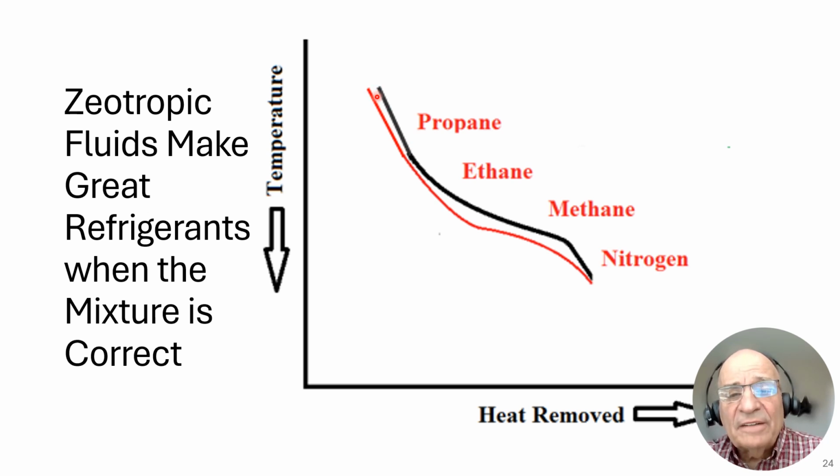One is that there's very little distance between the two. That's great because that means it's high efficiency. Here it gets a little bit mismatched, so it's larger, it's less efficiency here, less efficiency here. Now you can improve this by modifying the refrigerant components and by modifying the refrigerant composition.